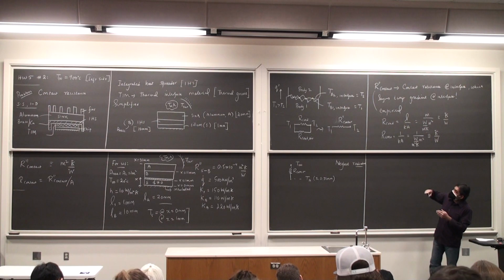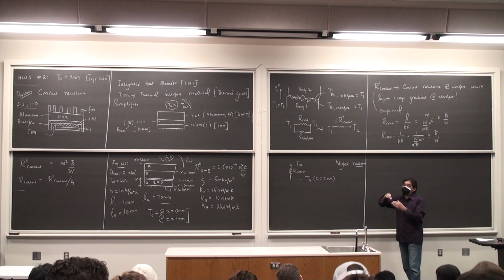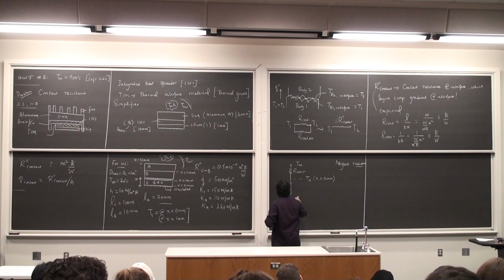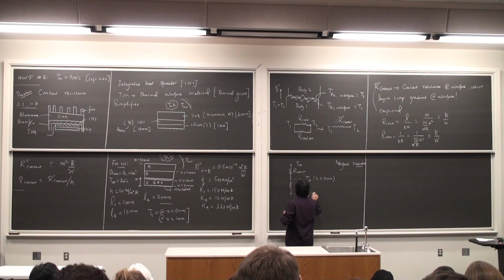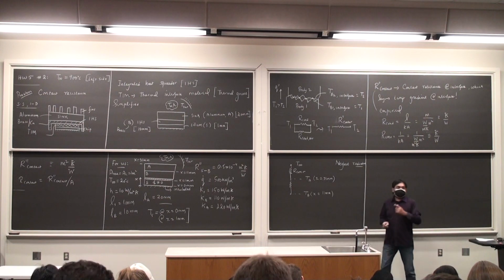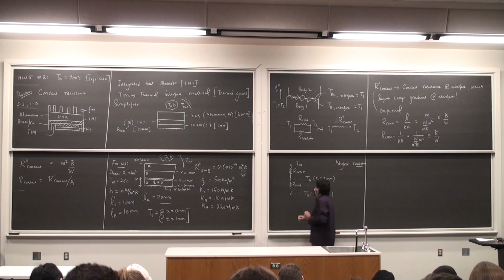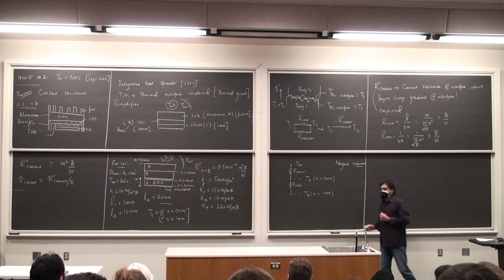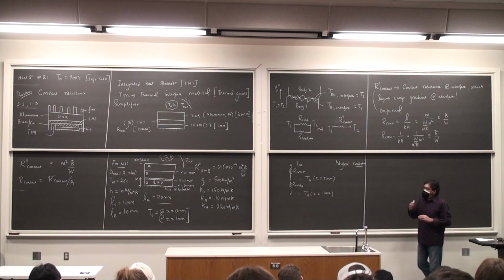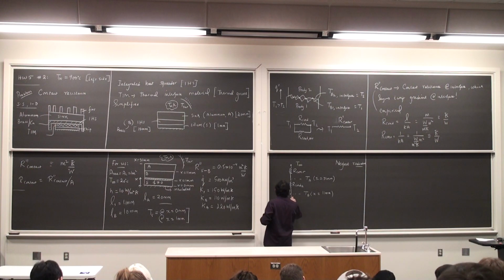So I can have a resistance network between B and A. In reality, there is a contact resistance. We'll get to it in a minute. So this is going to be TB at x equals 11 millimeters, and there is a conductive resistance in between them. So this is our conduction as I pass through the aluminum body. So this is our conduction A. Then I have the contact resistance. Okay? So I have our contact.